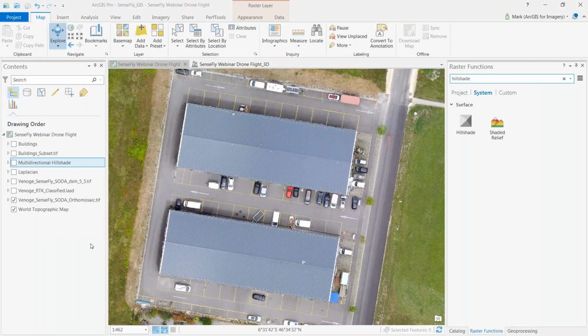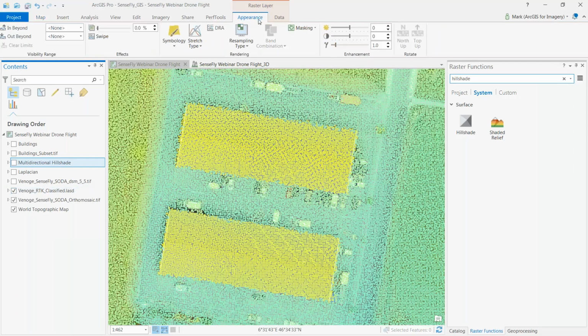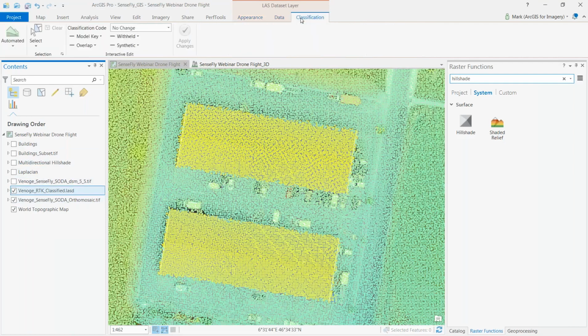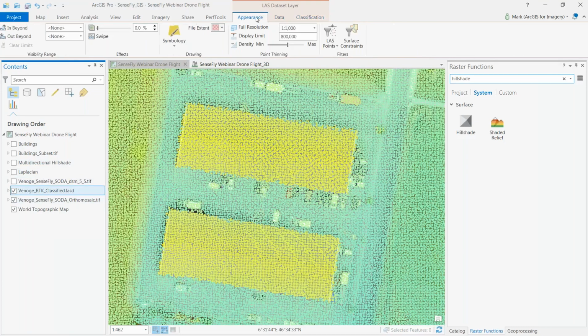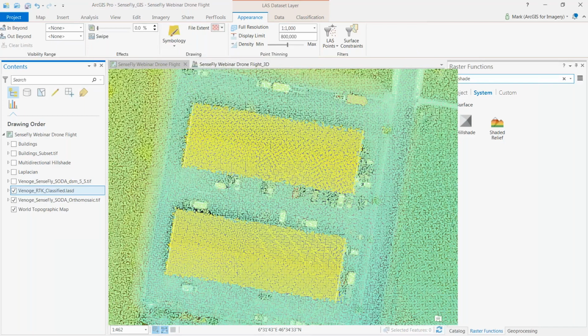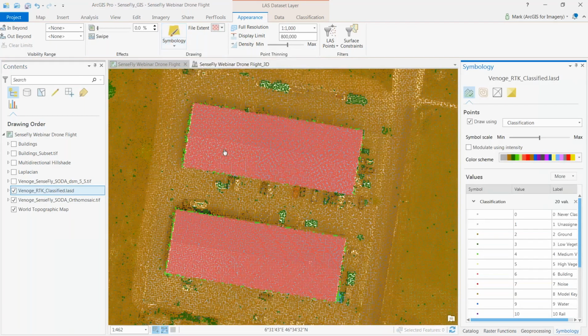Now, one of the challenges when working with point clouds derived from photogrammetric processes like drone to map is the points are not classified. So we can see the values by height, but unlike traditional LiDAR, if I wanted to view the points by classification like building or ground or some of the other categories, I couldn't do that unless I've gone in and manually classified these.